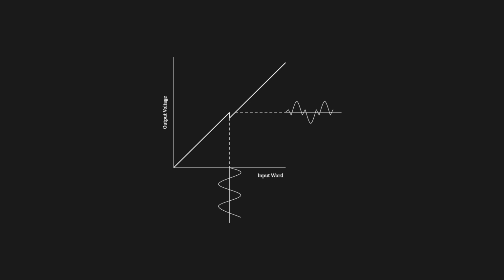Zero-cross distortion happens where an audio waveform crosses from positive to negative or vice versa. Changes in current or bit switching speed can create small errors and glitches at this point. This type of distortion can be reduced by precisely calibrating the most significant bits using a sign magnitude setup or employing separate DA converters for the positive and negative sides of the signal. Sigma-delta DA converters do not produce zero-cross distortion.